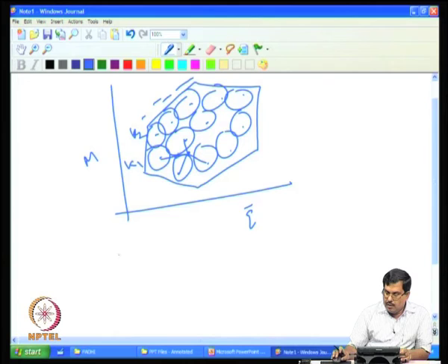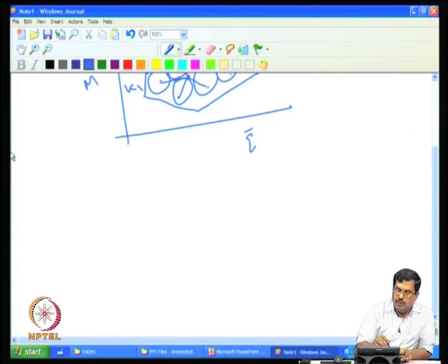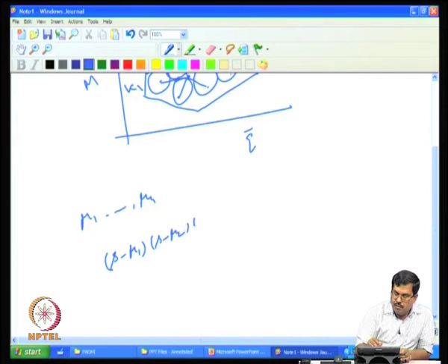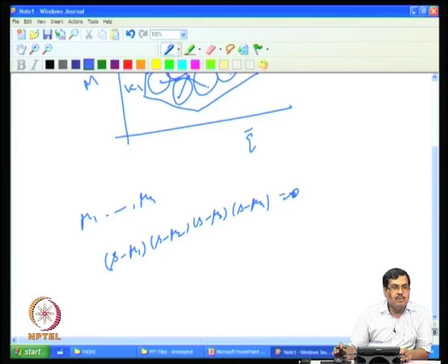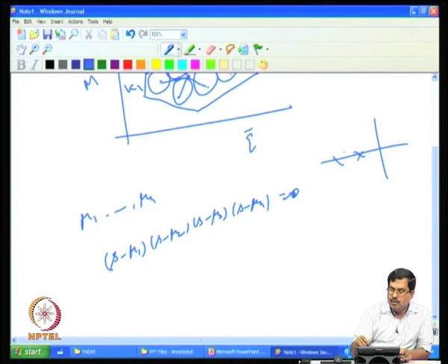So, you have, let us say, mu1 up to mu4. These are the desired eigenvalue locations, like whatever we did in pole placement control design. So, what you do here is s minus mu1 into s minus mu2 into s minus mu3 into s minus mu4 equal to 0, if you put that. Then that means the pole locations are certainly mu1, mu2, mu3, mu4, which are stable, whatever way you select. These are locations whatever you select.